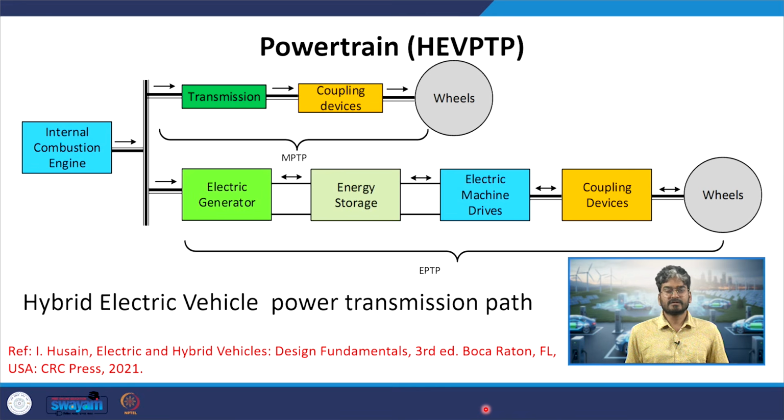The IC engine generates energy by burning the fossil fuel, which drives the vehicle, and in turn when the vehicle is driven by the mechanical path, it charges the battery through regeneration. When hybrid electric vehicles are used, they have better mileage compared to conventional vehicles because of the presence of the electrical path which aids the IC engine.